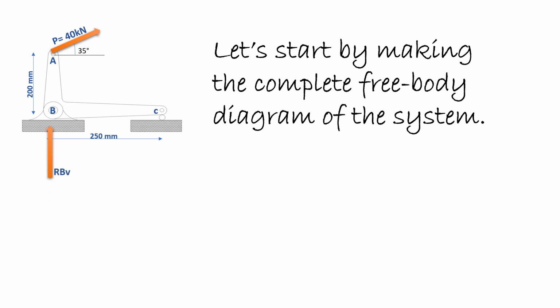So we have here an upward RBV. This is just an assumption, but we know that there is a vertical force or a vertical reaction acting there, since that is a pin connection. And also we have a horizontal reaction force which is RBH, and also we have a vertical reaction at this roller. So we also have this 40 kilonewton inclined at 35 degrees with respect to the horizontal.